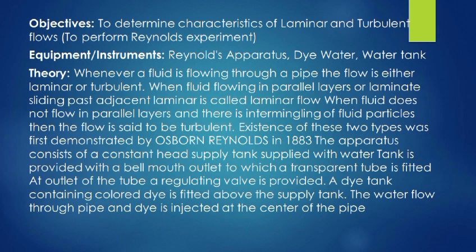The apparatus consists of a constant head supply tank supplied with water. The tank is provided with a bell mouth outlet to which a transparent tube is fitted. At the outlet of the tube a regulating valve is provided. A dye tank containing colored dye is fitted above the supply tank. The water flows through the pipe and dye is injected at the center of the pipe.